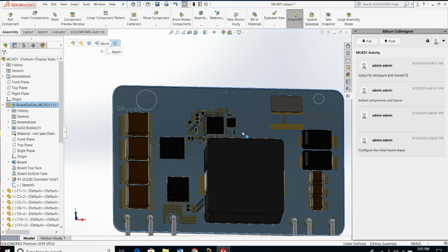I'm not interested in moving traces. For example, when I'm making an embedded transformer, those things are more easily done in a mechanical tool than they are in Altium. To make a spiral track or a special shape where a ferrite core can clamp around, doing that design in MCAD, pushing it into the board as copper structure.